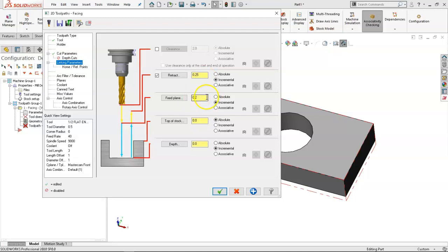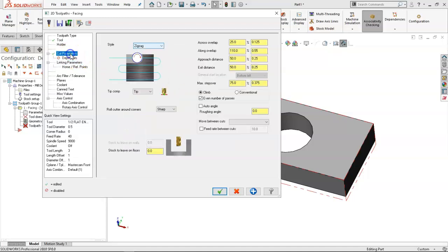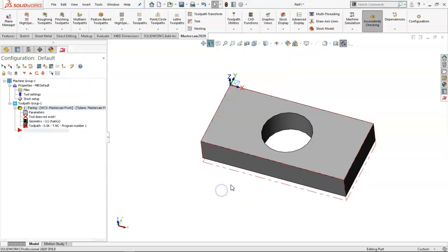make sure that I'm not wrapping into stock if I haven't given it enough on those extensions, which were the across overlap, approach distance. So we've given it the radius of the tool, which if we have oversized stock and we've set our 0 internal, we're going to touch a little bit. So maybe that goes up to 60 or 70% until we know what we're dealing with.